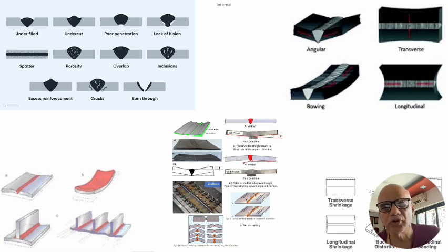It is not a volume defect, it is a planar defect, a crack, and those are very difficult to take up under the load. Cross-sectional area in that particular plane drastically reduces, and the weld cracks or the entire equipment has a failure.